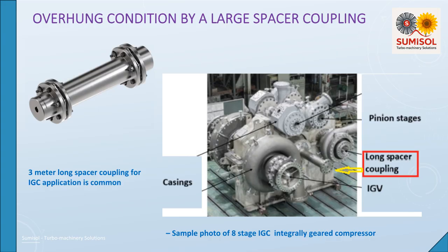Large gas and steam turbines are ideal applications where the diaphragm coupling's diaphragm can bolt directly to the turbine flange, thereby giving the best center of gravity location relative to the turbine bearing. In summary, the use of large spacer couplings requires careful engineering calculation of the bending and torsional moments acting on the shaft ends, particularly for high-speed machinery.